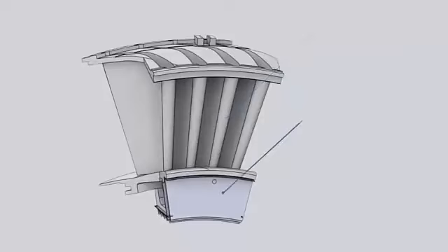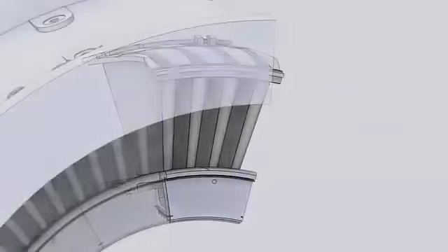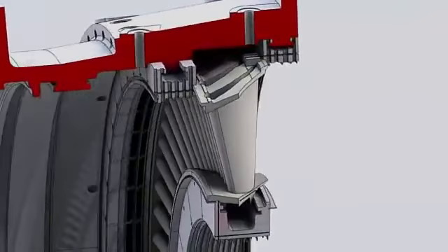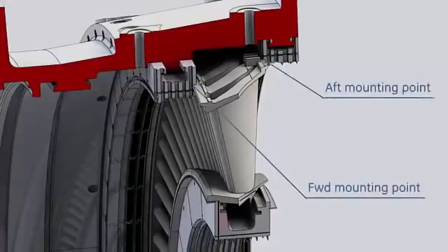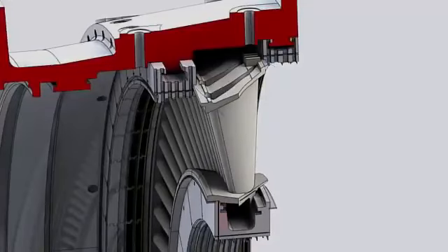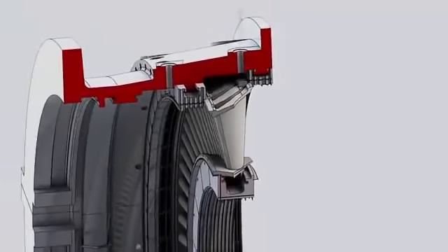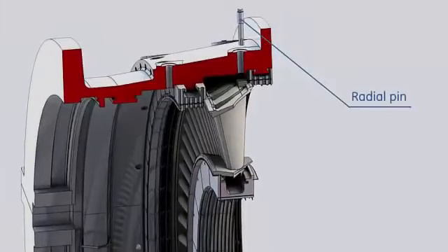A diaphragm segment is also attached to the inner sidewall of the nozzle. The third stage nozzles are not air-cooled. These segments are installed to the stator in the same manner as the second stage nozzle. The third stage nozzle is supported by the second and third stage shrouds. The nozzle segments are held in the circumferential position by radial pins from the turbine shell into axial slots on